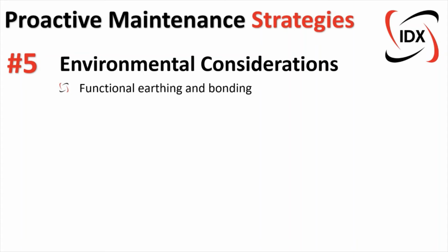And this has become more and more prevalent because functional earthing and bonding is absolutely critical to the health and sustainability of networks on site. What the standard pretty much covers is about 6 recommendations, and the recommendations explain why you implement that recommendation and how you should implement it. Some of the recommendations are like the power distribution system that you're implementing. They recommend you use TN-S, which is where your transformer supplies your 3 live phases, a neutral, but a separate protective earth line from the transformer. And you're not using TN-C or PEN bridges, anything which can cause damaging earth loop currents.